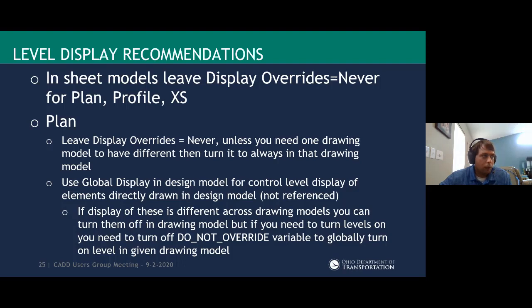Okay, so I skipped ahead of that first bullet note. For sheet models, I think leave the sheet models alone. Don't try to control level display in the sheet model, right? Leave those at never, and let those control everything from the drawing or the design depending on the situation. So I don't recommend touching that one, unless you have something drawn directly in it.